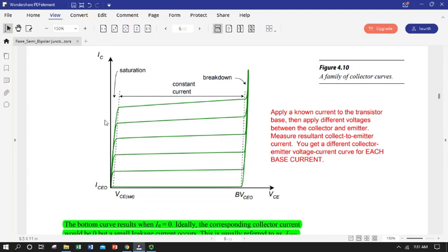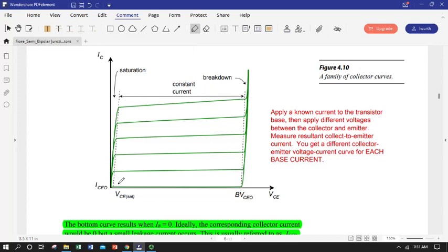So we've got collector current on the Y, and given that base current's pretty small, this is the collector to emitter current transiting the transistor. This is the controlled signal. And we have collector emitter voltage on the bottom, so it's just like the voltage drop over the device, just like we talked about in DC. And these green curves are each separate plots. So somebody went in the lab and they took their transistor and they put across it a variable voltage supply like their DC power supply, and they put a shunt resistor in line with it, and they measured the current. They kept turning the voltage up between the collector and the emitter, gave it more voltage on the x-axis, and plotted these curves. And they got a different plot depending on how much base current they were giving the device.